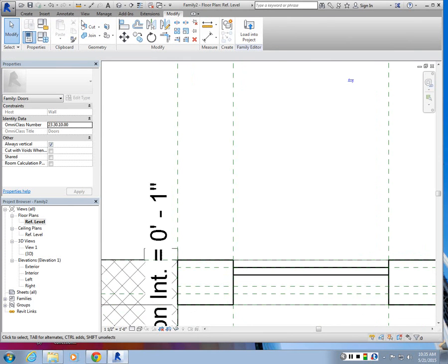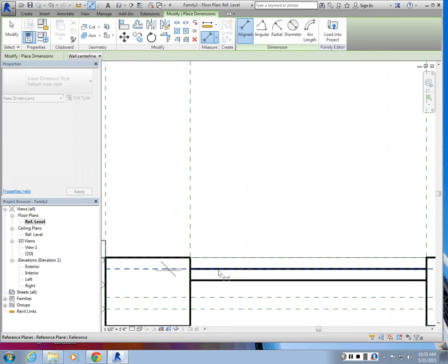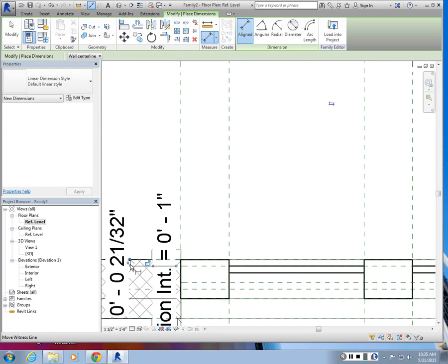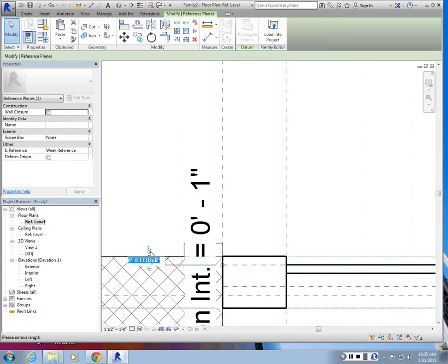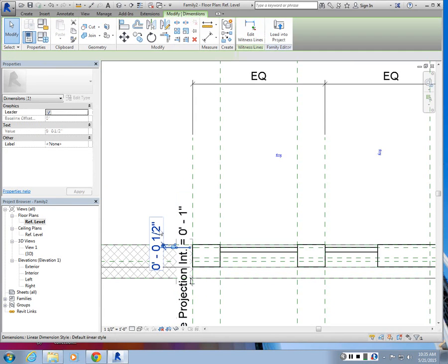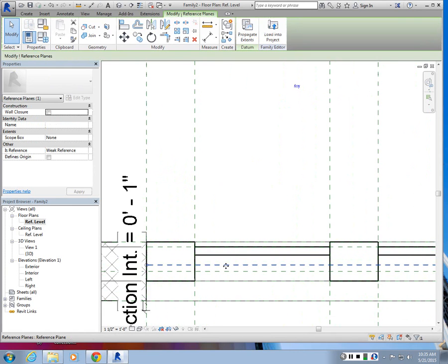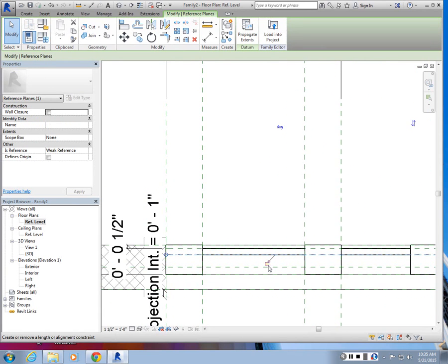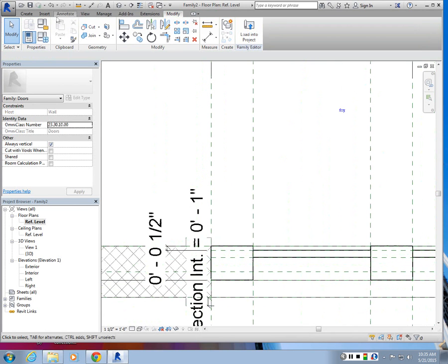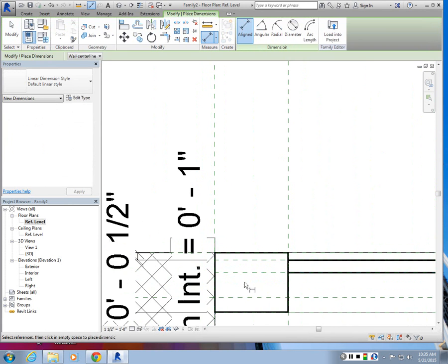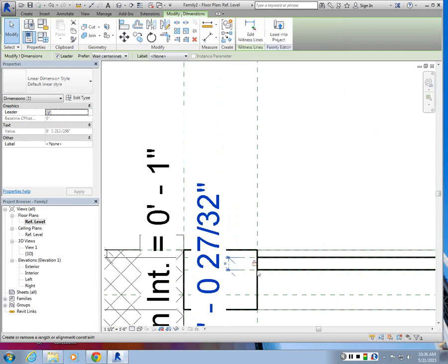Or if not, you could just go to annotate. Annotate these 2. Choose this plane. Give it like a dimension, 0.5 inches. And then you can choose that dimension and lock it. Right? Same thing for this guy. So you can lock this relationship, as well as you can create another annotation there. From this to that. If I want to keep that, you can just lock it.